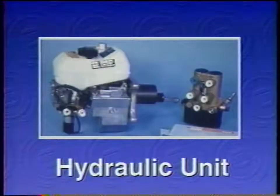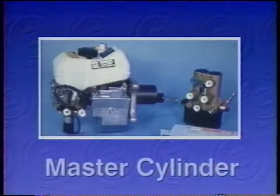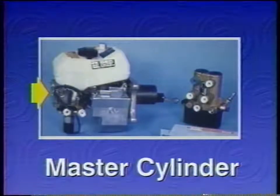The hydraulic unit integrates the functions of the modulator, master cylinder, and booster assembly. It's the heart of the Bosch 3 ABS system and contains several components and sub-assemblies. The master cylinder is located in the upper portion of the unit. It works in the usual way, except that pressure is stored in an accumulator rather than by the mechanical assistance